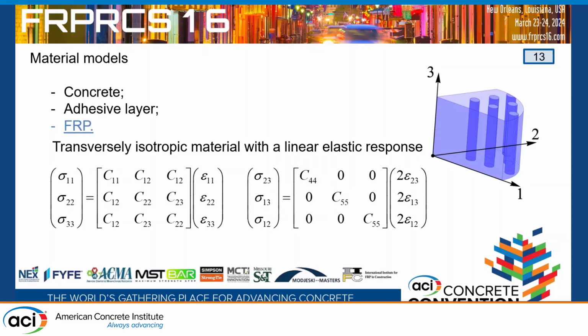Okay. But usually, this was uniaxial. Unidirectional, yes. But in the transverse direction, to the fiber, you don't consider the strength in that direction. A long time ago I made experiments along the fibers, normal to the fibers, and at 45 degrees with respect to the fiber orientation to obtain the 5 constants.